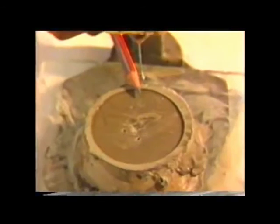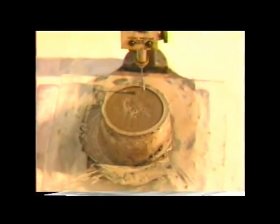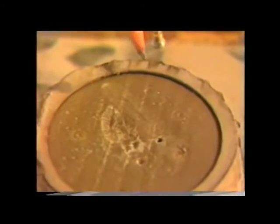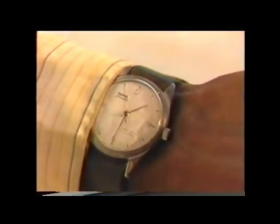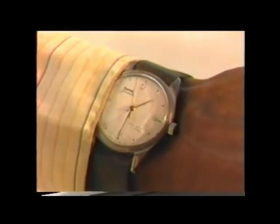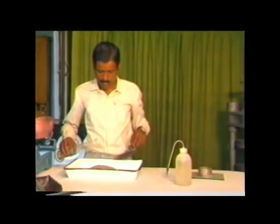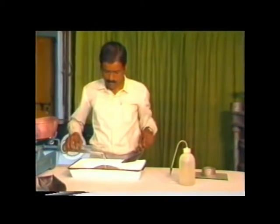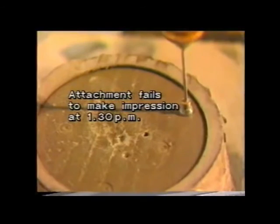After the elapse of initial setting time, observations with annular attachment are made at appropriate time intervals till the needle makes an impression on the mold while the attachment fails to make any impression. Final setting time will then be equal to the difference between the time the moment water is added to the cement and the time at which attachment fails to make an impression.